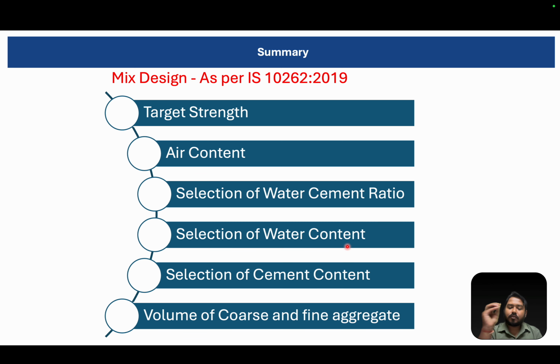So in that case, you have to take the deficient amount divided by 0.05, because that is the change in water to cement ratio. Then you multiply by 0.01, the excess aggregate you are going to add. So this gives how much extra aggregate I am going to use. Once you have the excess aggregate, you add it to the volume of coarse aggregate I already found based on 0.50, and that gives the final value. So you are getting the volume of coarse aggregate.